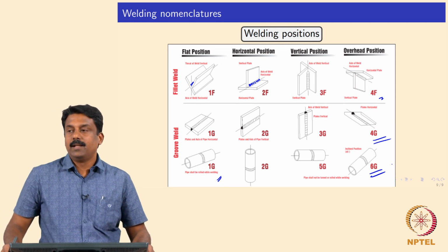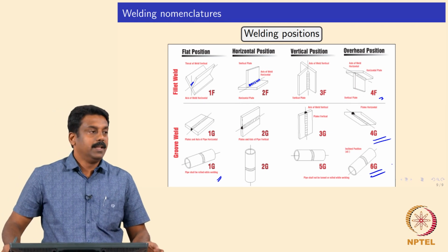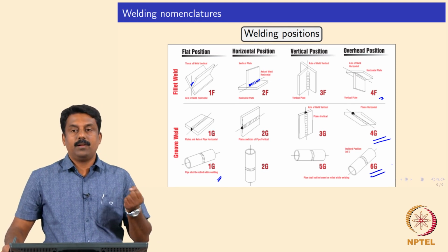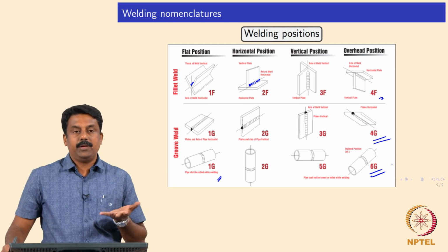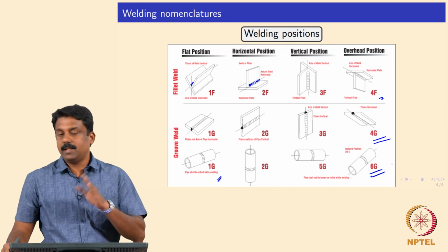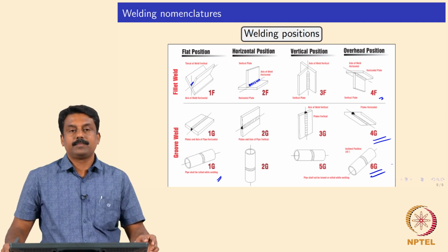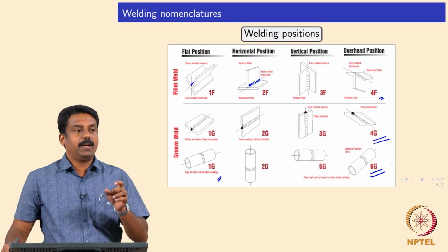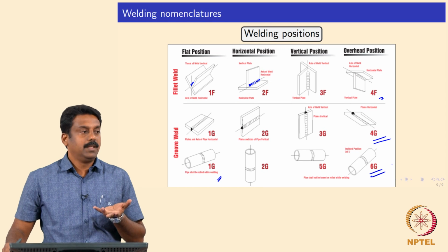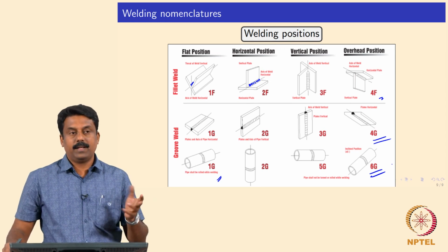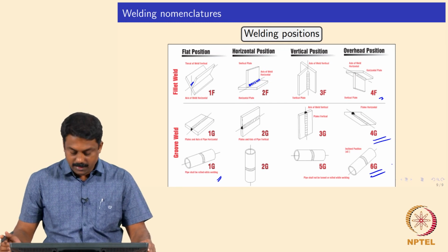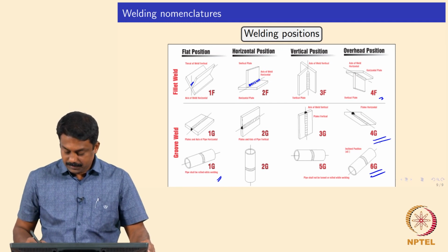Okay. So 6G welding is generally done by extremely trained operators, because you will have to make sure that when you are depositing, you have welding procedures adjusted for each position as well as each pass, because you need to make sure that when you are depositing, the weld should flow and then you form the fillet without any defects, for example undercuts or overlaps, right. Is it clear? Any questions so far?